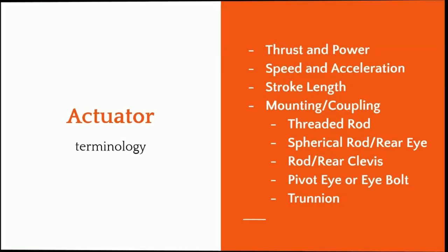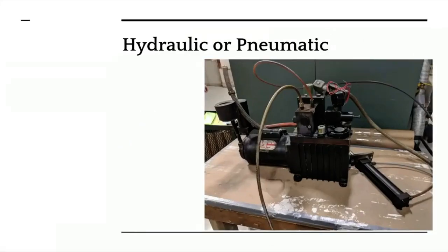web guiding system. The older actuators were either pneumatic or hydraulic. You had a hydraulic pump pumping a double acting cylinder and moving the web guide structure. These were more common in the 50s and up to about maybe the 90s, before electromechanical actuators started coming into the market. You could have pneumatic actuators or hydraulic actuators. The hydraulic actuators have the advantage that they can provide high thrust and can shift large loads quickly. Even now in the metals industry, hydraulic actuators are pretty common.